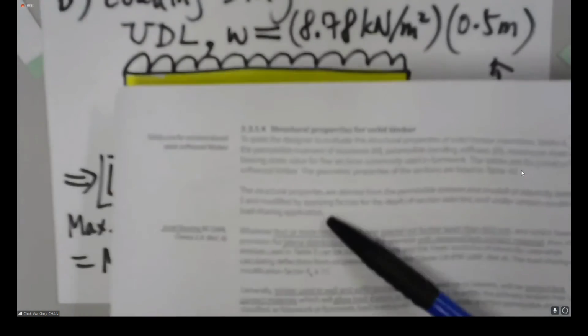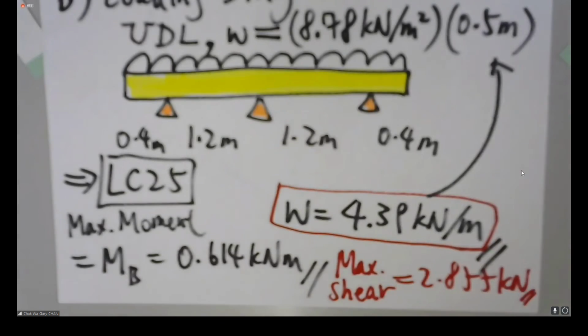of your supplementary note, the top of it. You can find it from the British Standard. Talking about when you consider load sharing, there should be 4 or more timbers. So in this example, you are checking the joist. You are having more than 4 joists supporting the plywood. The plywood is the face contact material.